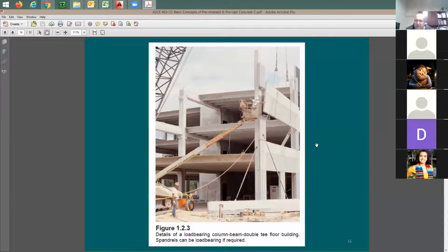The problem was the noise, because you have the ramp and people start to speed up while they're going down, and you get lots of sound, and they couldn't stop it. I mean, they tried their best. They said, what can we do? And they were told, okay, this is what you get when you do a structural steel parking structure. This is one of the problems. Another thing was also the rust, because parking structures can be open to rainfall, and this can create some problems with the steel. It needs more maintenance, whereas here there's going to be less maintenance, because you can design your concrete not to crack if you want to.